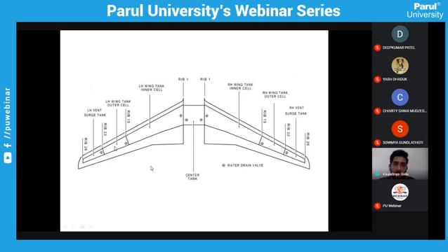Okay. There will be 2 valves. This is what you call a pressurized open valve, where what happens is like a seal. If a certain amount of pressure is applied, the seal gets automatically broken and the fuel gets dumped out. And this amount of pressure is dependent on the amount of fuel being stored inside the tank. So pressure is nothing but another form of weight, right? Pressure is force per unit area, right? So in a certain amount of area, if you are dumping more fuel, the seal breaks and fuel gets dumped. Okay. It won't break otherwise.